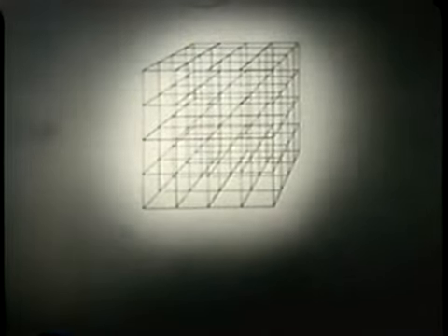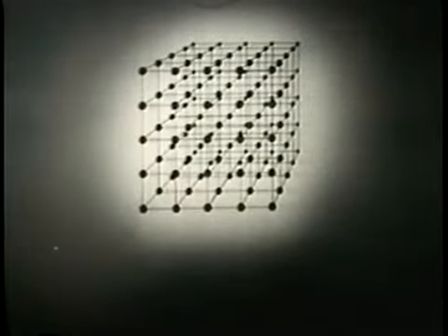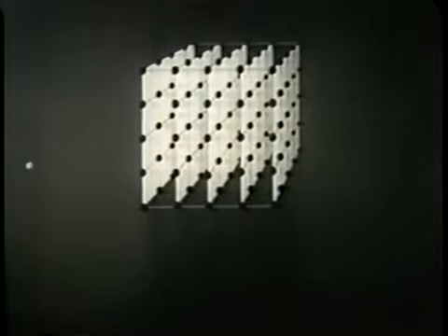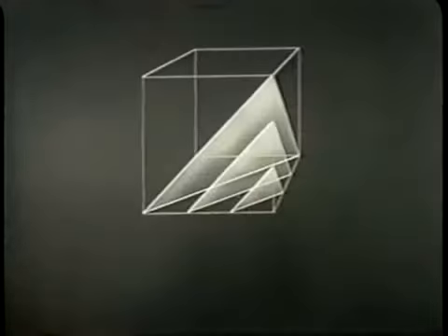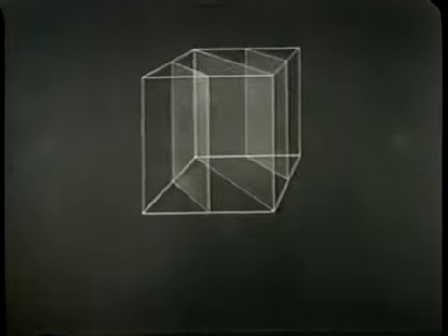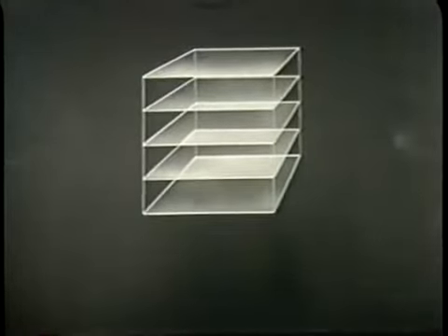Within the space lattice, metal atoms exist in families of parallel planes with definite spacings between the planes. It is along these planes of weakness, called slip planes, that the crystal is most likely to glide or slip when deformed. These are important slip planes, along which movement may take place in the aluminum crystal. Through such movement, a crystal may undergo two types of deformation. The first is called elastic deformation.